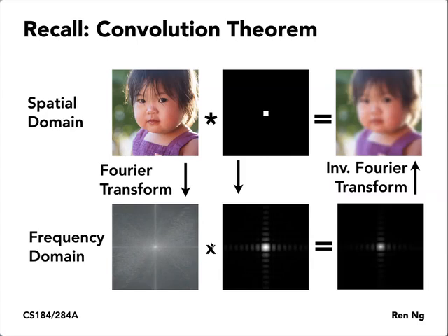So overall, implementing a convolution in the frequency domain is O of n squared log n complexity, versus O of n to the fourth in the spatial domain if you had a really large filter kernel, okay? So usually if engineers are faced with implementing a convolution kernel in the spatial domain, whether that's the code they're going to write or the ASIC logic they're going to lay out, they will be forced to choose a very small filter kernel. If you want to run a large filter kernel, then that puts a very strong bias towards considering doing it in the frequency domain, okay?